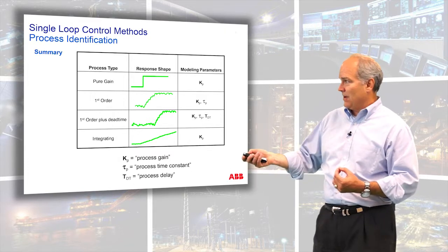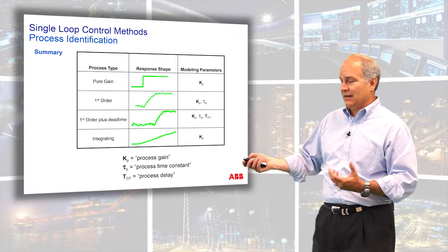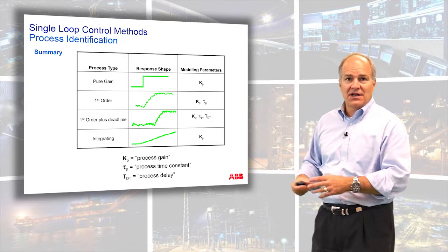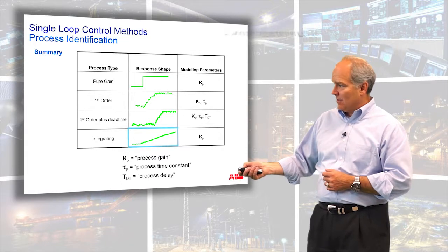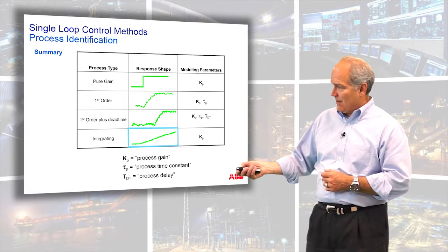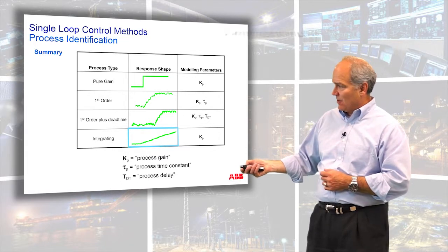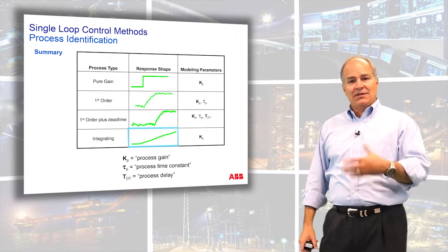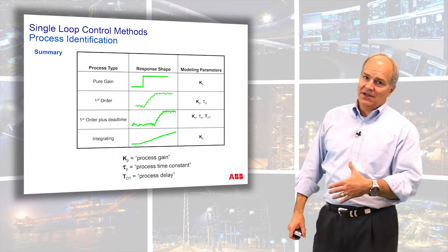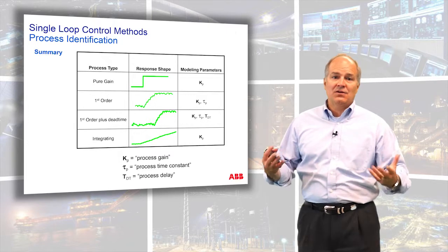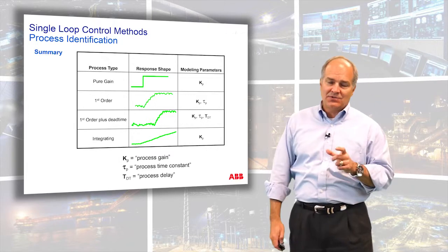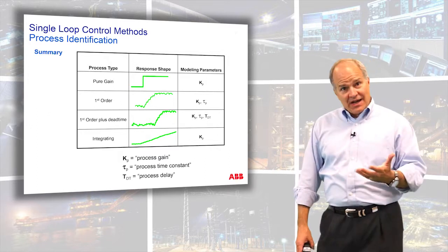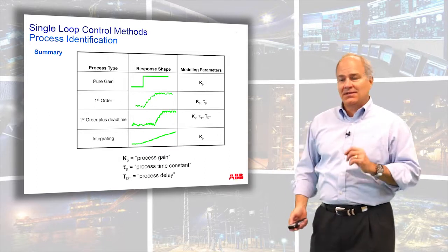So for the top three that stop themselves, the gain is calculated the same way: change in measured value over the change in the output that produced it. But how can that possibly be here? It depends on time. If time keeps moving, the change in the output keeps growing with time. So it can't be the change in the measured value over the change in the output. Time has to be incorporated into that particular parameter. And that's what we're going to talk about, and that's what makes tanks a challenge, but I'm going to show you a shortcut that makes them easy again.